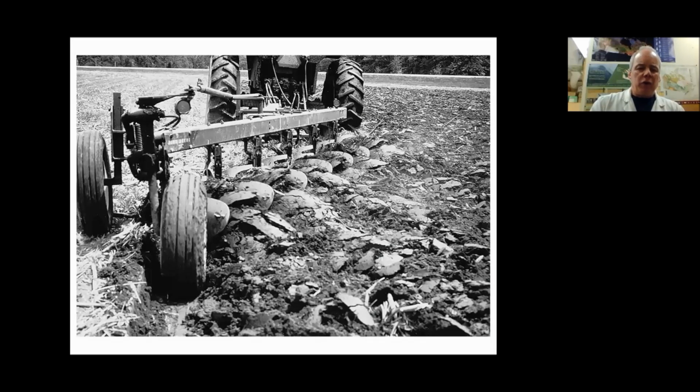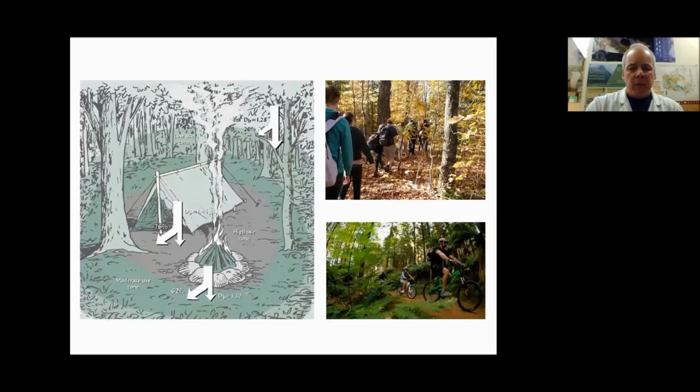Again, in agriculture, farmers use best practices to try and avoid soil compaction. High flotation tires, again, spreading the weight of machinery out, and seasonal restrictions. You're not going to do this kind of activity on a really wet soil, because with a wet soil you're going to get a higher compaction amount than you would on a dry soil. So there are methods used to minimize the compaction that would occur.